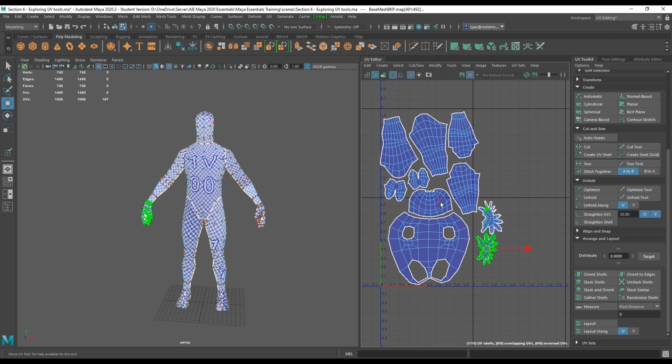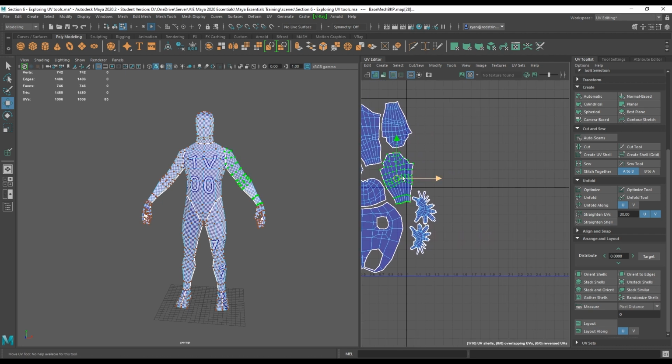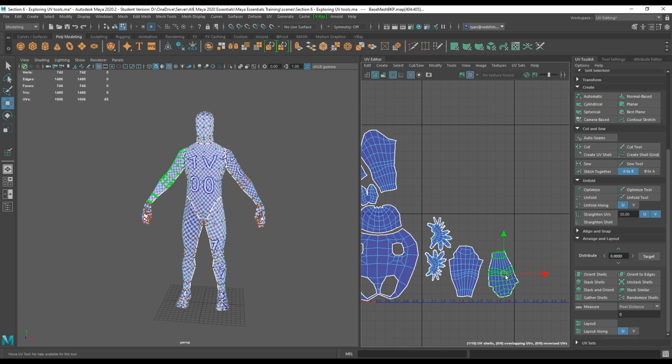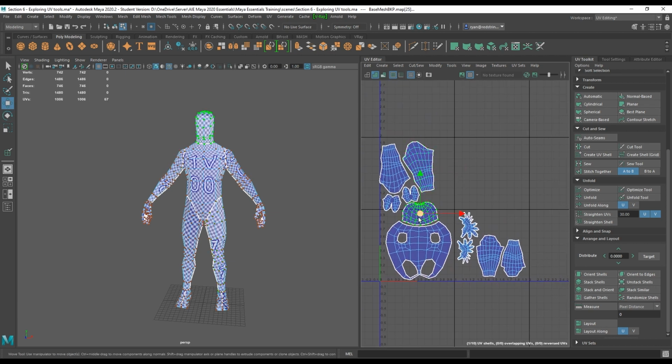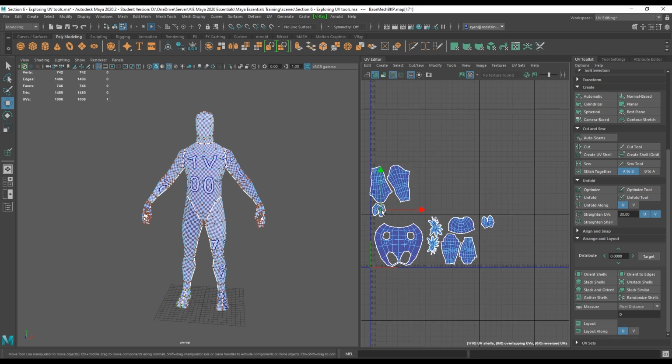Have them come in. I can go take this leg, shove it in there, take this leg, shove it in next to him. So what I'm now currently doing, I'm using multiple UV tiles and spreading my UV islands across the tiles, because now this one model will have potentially 3 texture maps to be able to contain all the texture information. So like I said before, the smaller the squares, the higher the resolution.